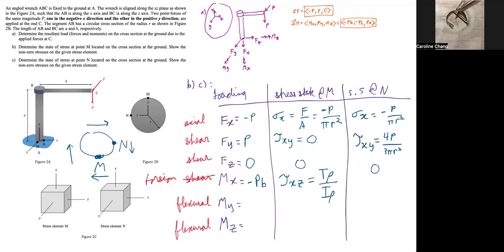So knowing that the polar moment of inertia for a solid shaft is given by that formula, we can now substitute our known values. But the direction for the shear stress over here is actually given by observing the direction of the shear stress on the diagram.